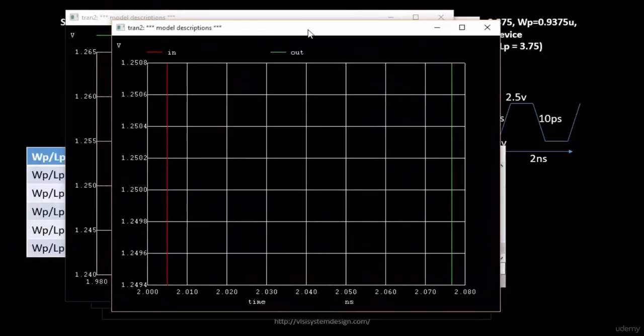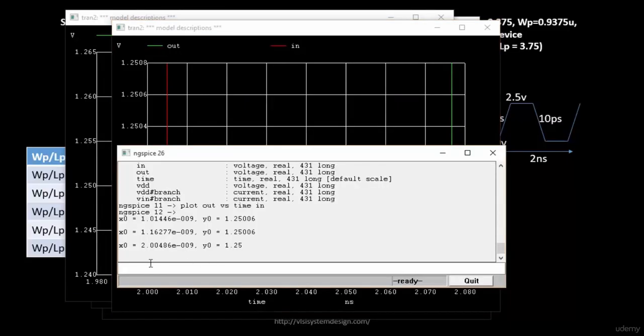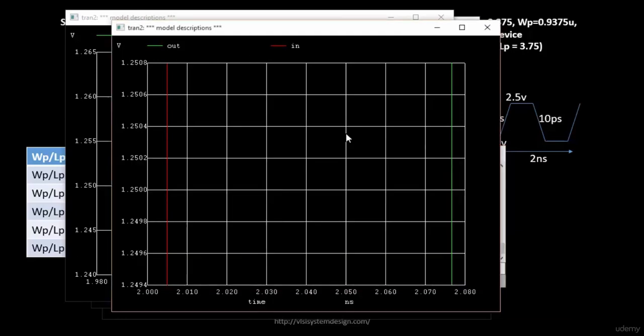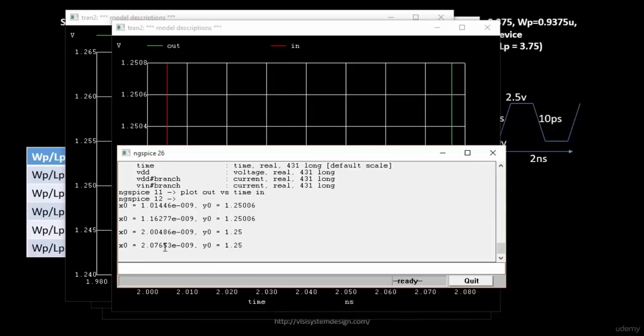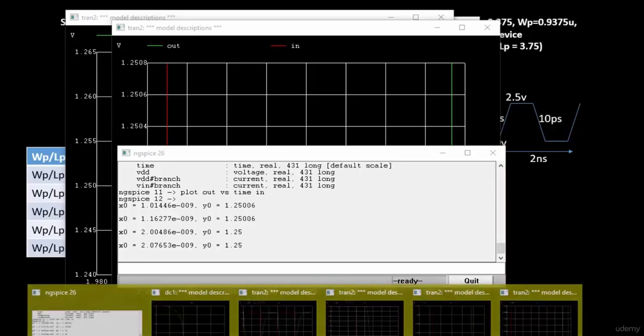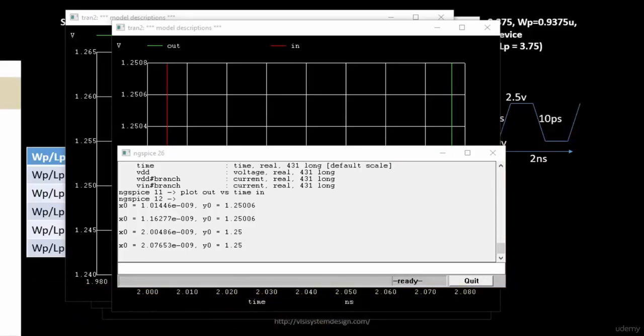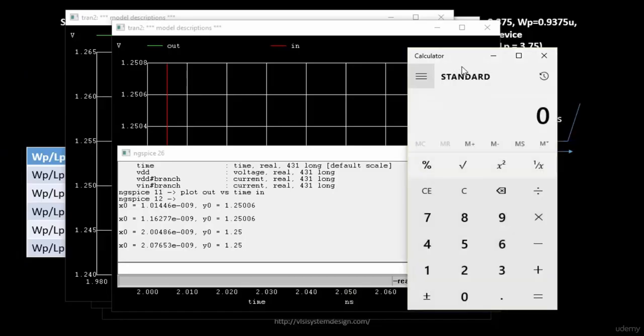We'll again bring up our SPICE simulator. Now we have the netlist present over here, so let's copy it. We'll source the circuit file .cir. Okay, now we'll run it, and we'll set the plot.